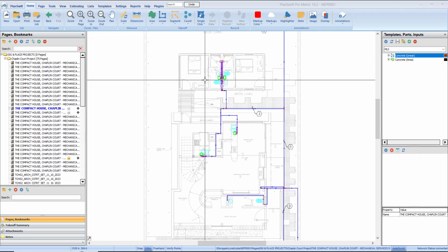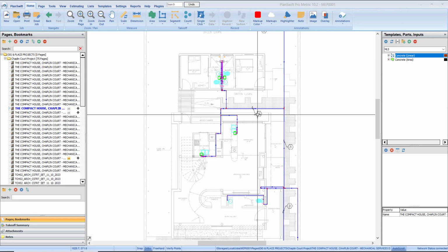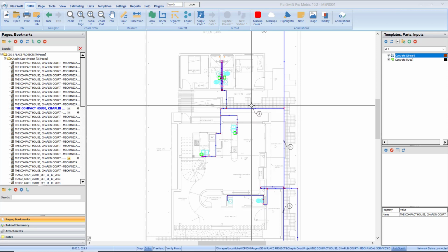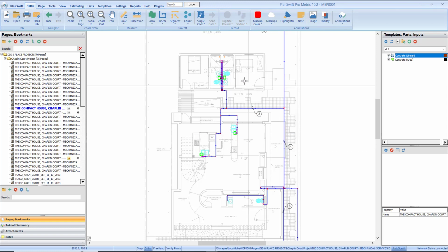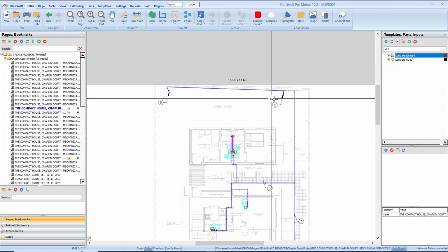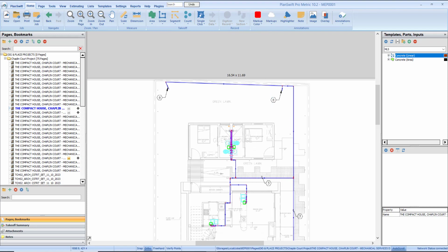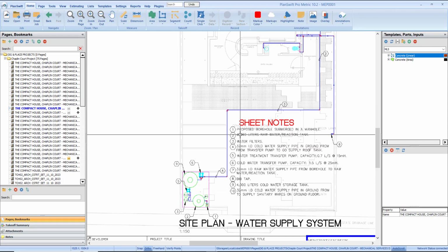Okay, so once you are ready to measure, then another thing I want you to pay attention to are these numbers that you see on these drawings or that are being attached to the pipes. So this blue line represents the pipe layout, and these numbers also represent a particular item here on the plumbing drawing.